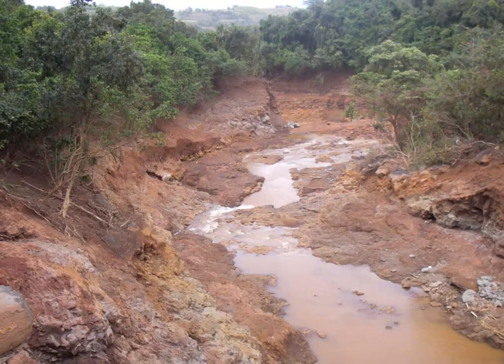Besides making the point that this channel shows the irregularity of a surface depending on more than just the material that it's made out of, this also shows the effect of excessively high scour velocities. And oftentimes because of urbanization, or the process of people putting in a subdivision where it used to be a forest, or putting in a shopping center where it used to be a grassy meadow, any sort of natural cover is going to be allowing infiltration of rainwater into the soil.